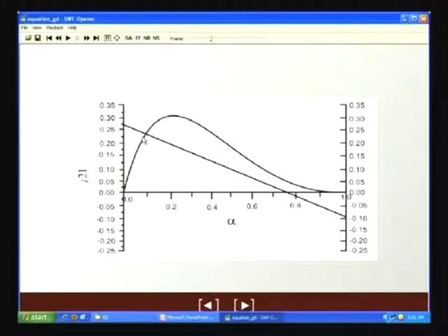Fine. Notice one thing very interesting: in this particular case, no matter how much J1 is increased or how much J2 is increased, the point of intersection always lies along this portion, or in other words, for a small value of alpha where bubbly flow exists.